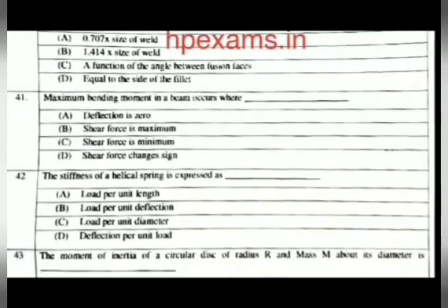Maximum bending moment in a beam occurs where? And the right answer for this question is where shear force changes sign. Or it can be point of contraflexion. The stiffness of a helical spring is expressed as? And the right answer for this question is option B, load per unit deflection.